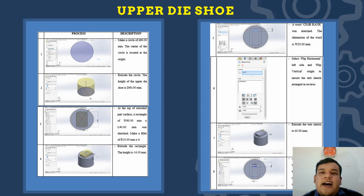This is the upper die shoe sketching step. The important method of doing this is the sketching of the text on the face of the stamping die. The text needs to be flipped horizontally. The method is we need to select flip horizontal left side and flip vertical to origin. It is to ensure the text sketch is arranged in reverse, as when we produce the gold bar, the text sketch will start from the left side.